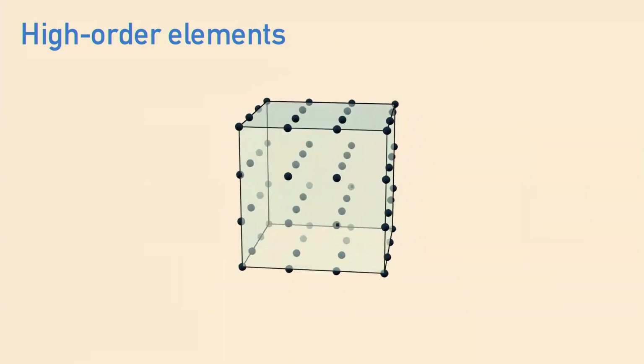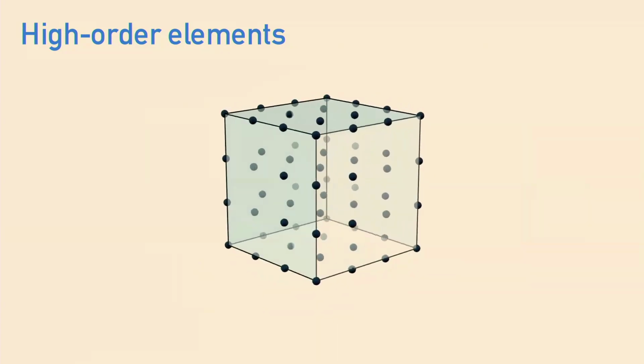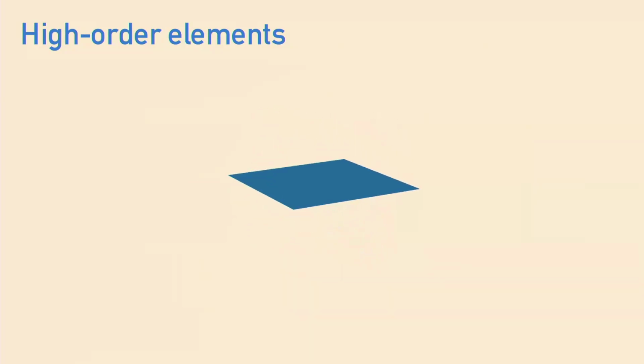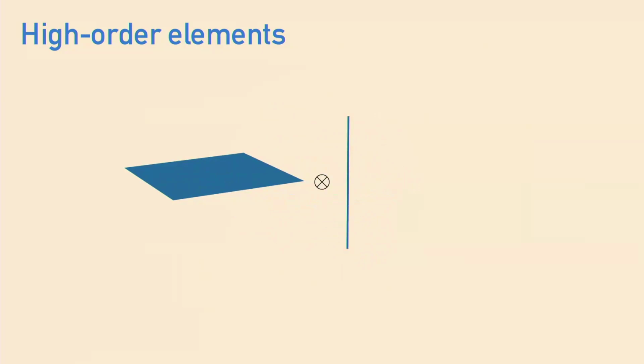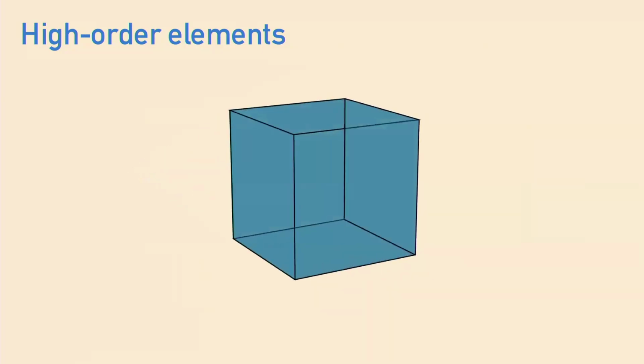So a well-known solution to this problem is to use something called sum factorization, which is where you start with the element in 1D, and then you exploit the tensor product structure of tensor product cells to combine two of the intervals together into a quadrilateral element. And then once you have that, you take that quadrilateral element, take its tensor product with another 1D element, and you get the hexahedral element.